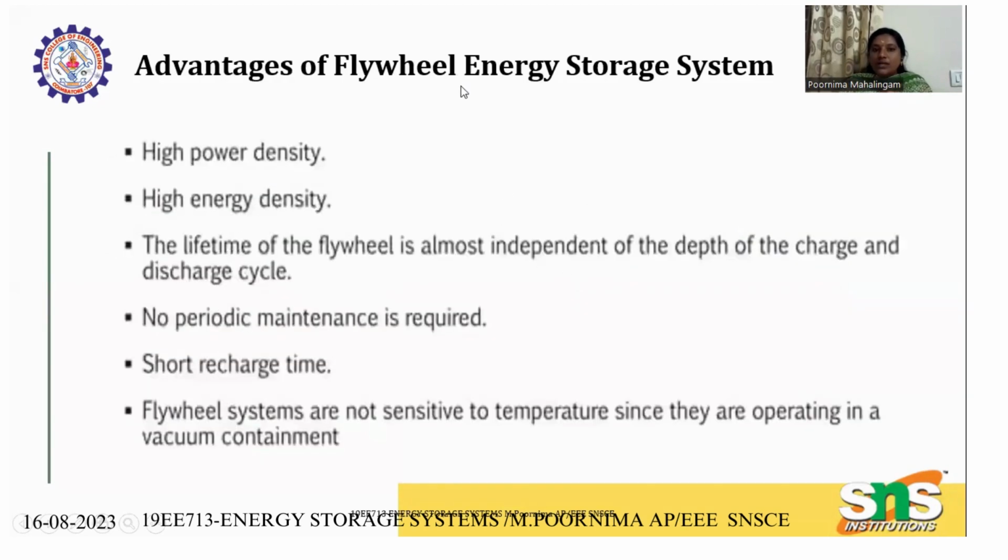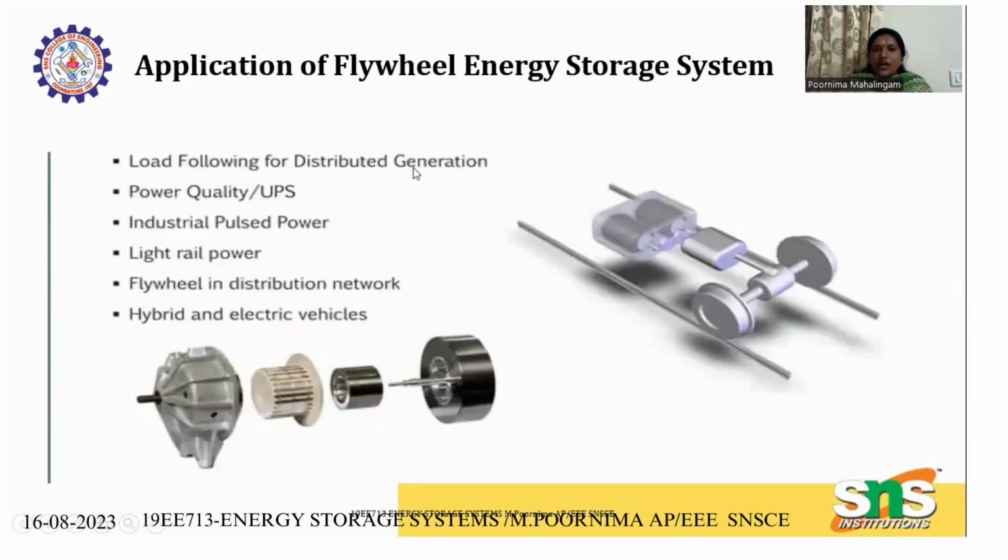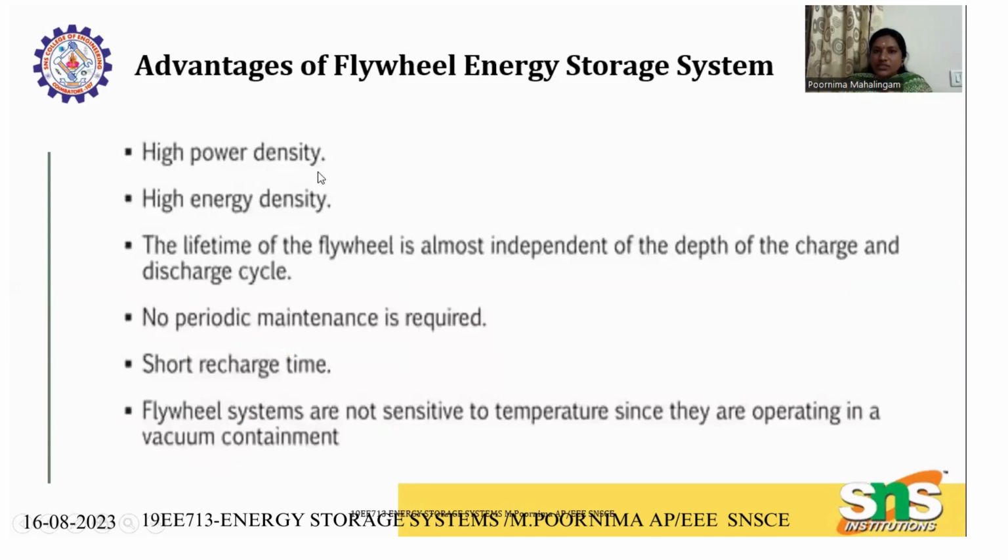The main advantages are high power density and high energy density. The lifetime of a flywheel is almost independent of charging and discharging, the lifetime is good, and no periodic maintenance is required. Short recharge time is the main thing. Flywheel systems are also not sensitive to temperature since they operate in a vacuum container.